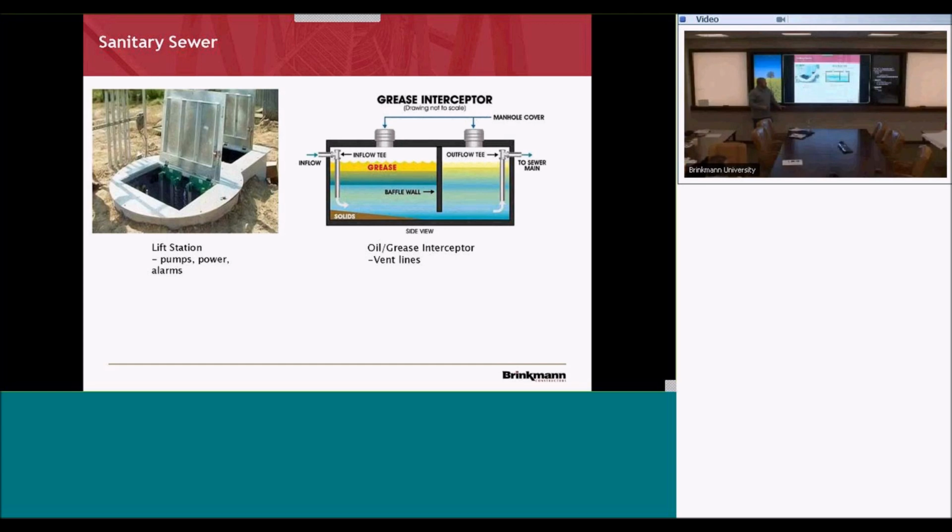But look at the size of them, the footprint. If you have a grease interceptor and it's a huge one out in the middle of a parking lot, because you have runoff and they're required to have it there, how big of an excavation is that going to be? How long is that going to take? It can really impact your schedule. So you want to pay close attention to those things.